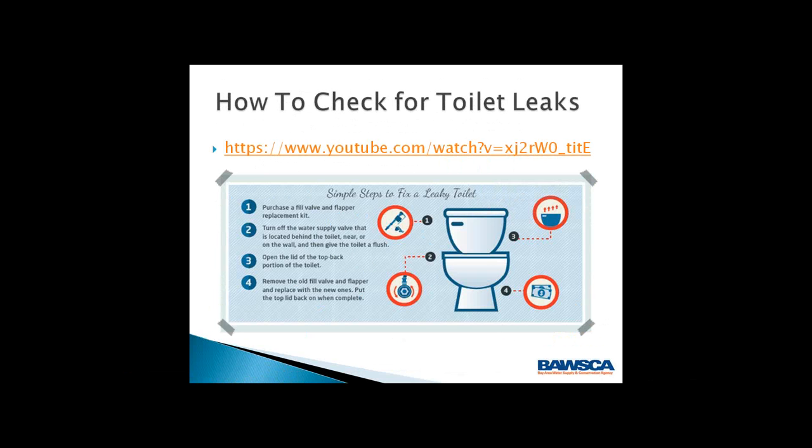So how to check for toilet leaks. A lot of people don't know if their toilet's leaking, and they see it on their water bill, and they're saying, why? We don't use this much, what's going on? So a great thing that you can do is actually buy dye tabs, and almost all water agencies offer these for free. They're very easy to obtain.